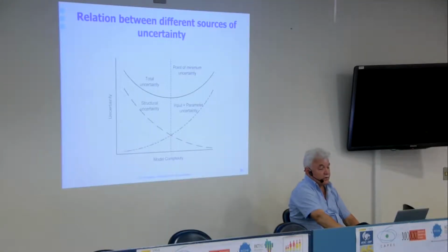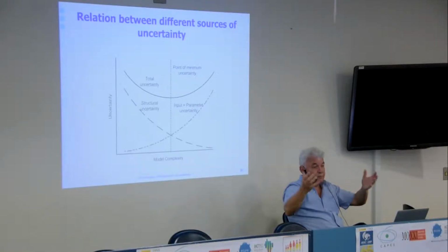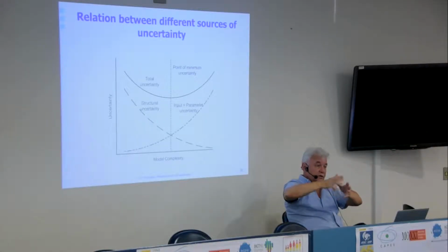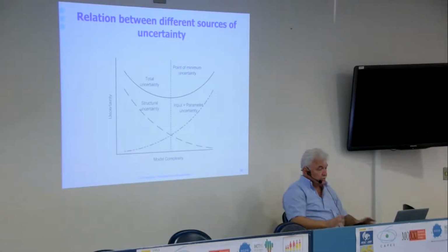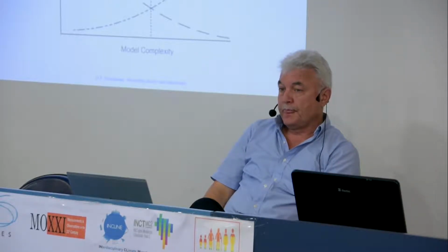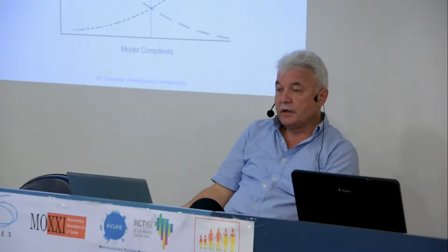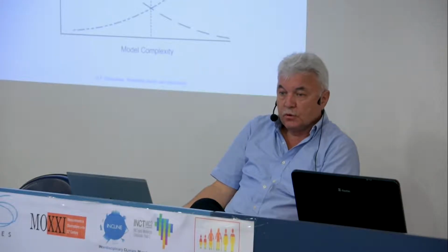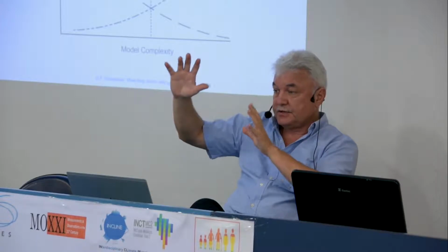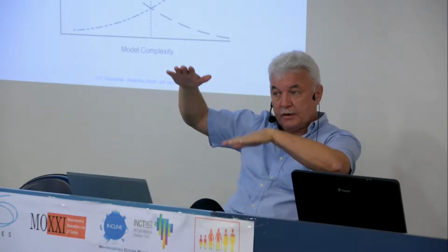And actually, in hydrology, the compromise here is the semi-distributed models. Like HBV has several components. Practically any model you can make semi-distributed, so you find these hydrological units. Like in SWAT also, you can pick these units based on some hydrological knowledge, and don't make too many of them, don't make 100 of them, because it becomes almost a distributed model. So several, where you could assess soil properties and update your parameters a bit.